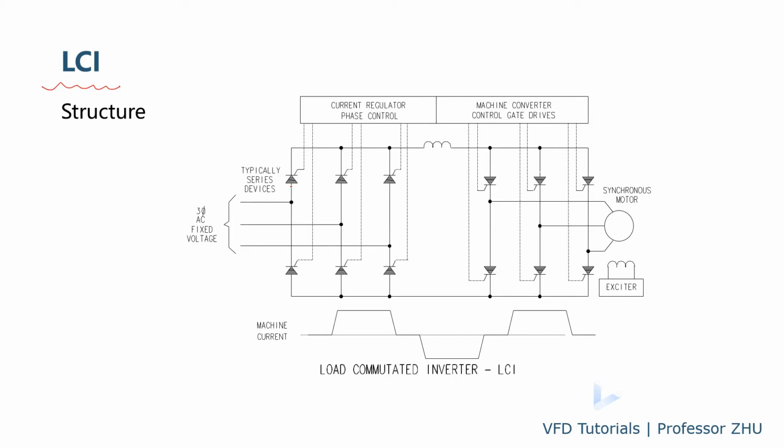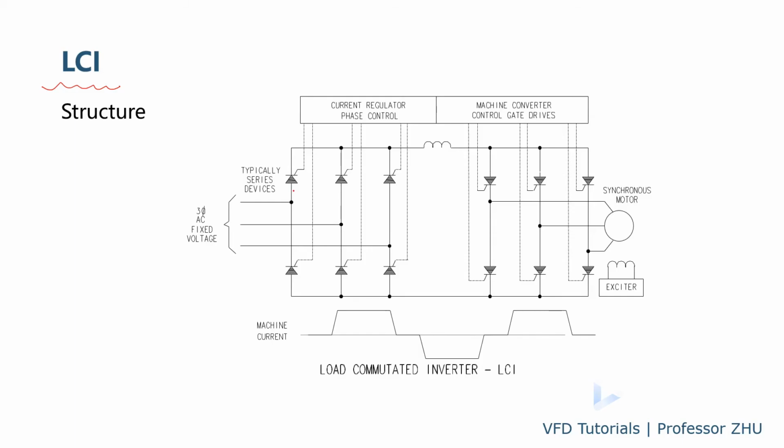So the power factor will be very low at low power output. Like if the motor runs at a very low frequency, then the load is very low, and because of the firing angle, the phase angle of the rectifier SCR, the input current is lagging the voltage with a very large angle, so the power factor is very low.